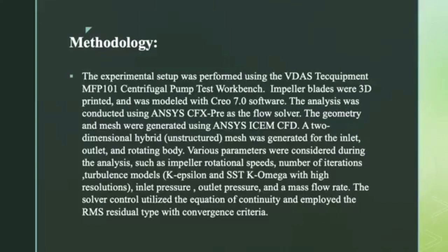Methodology. The experimental setup was performed using the VDAS Tech Equipment MFP101 centrifugal pump test workbench. Impeller blades were 3D printed and modeled with Creo 7.0 software. The analysis was conducted using ANSYS CFX-Pre and the Flow Solver. The geometry and mesh were generated using ANSYS ICEM CFD. A two-dimensional hybrid mesh was generated for the inlet, outlet, and rotating body.